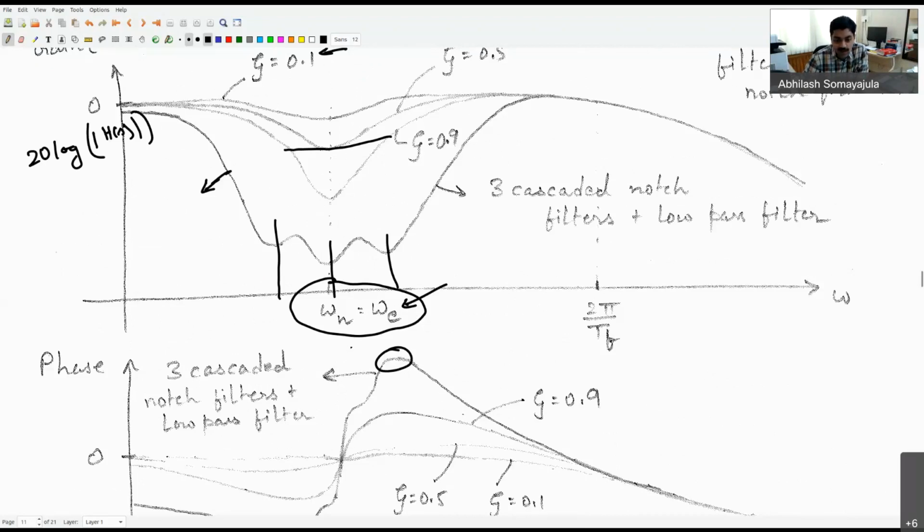So in which case, how do we go about estimating what the actual encounter frequency is which I should compensate for, right? The idea there becomes that you can look at the motions of the vessel from your sensors and then try to estimate where that encounter frequency is. Usually, if it's a single sinusoid, it is fairly easy to find it out. But if it is a spectrum composed of some more things, you may have a little bit of a tough time to figure out where the natural frequency or the peak frequency of the spectrum is.